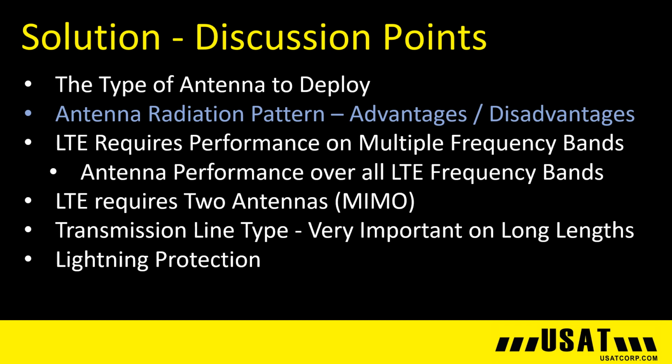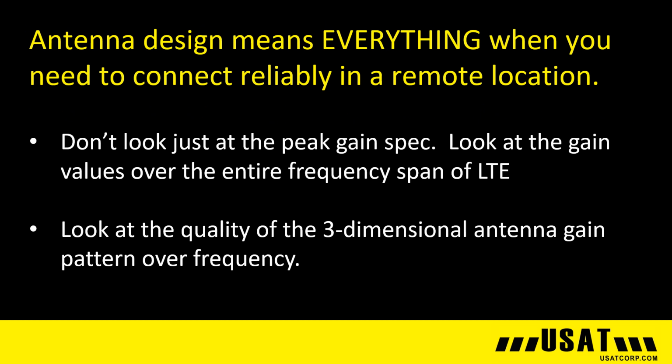Next, I'm going to talk about the radiation pattern of antennas. Antenna design means everything when you need to connect reliably in a remote location. A couple of key points here. Don't look just at the peak gain spec. Look at the gain values over the entire frequency span of LTE. And look at the quality of the 3-dimensional antenna gain pattern over that frequency.